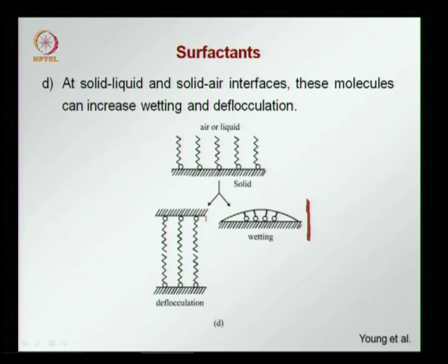You can also have a case where you want a hydrophobic surface, for example when we use a cement mortar or any other material for waterproofing. We do not want water to enter into the cement mortar and we would rather have a hydrophobic surface, therefore we can use a surfactant to make the surface reject water and ensure that water does not wet the surface.